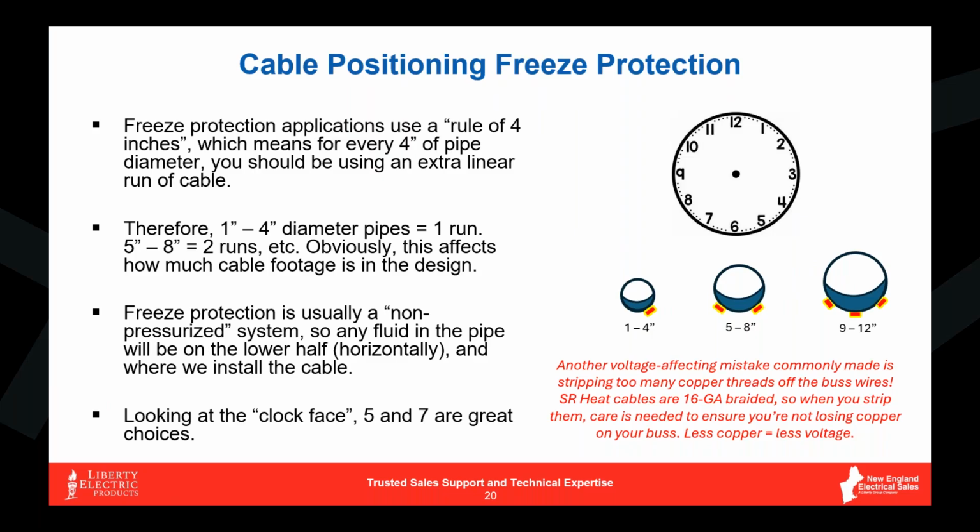Again, the biggest thing with putting the cables on the pipes is your terminations. It's really making sure that you have a quality termination. And quite honestly, for any PMs, estimators, or technicians that might be on this, I would give yourselves a solid half hour per termination. I know that might seem like a lot, but you can't strip this stuff back and just slam it in like you can a piece of 12-2 Romex.